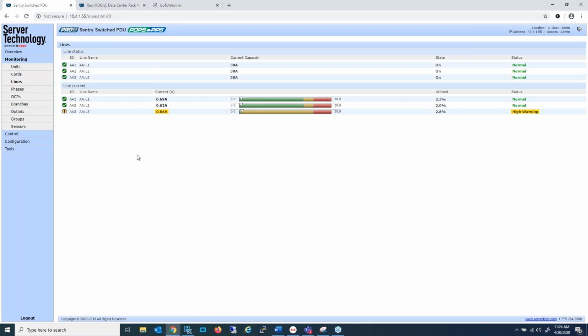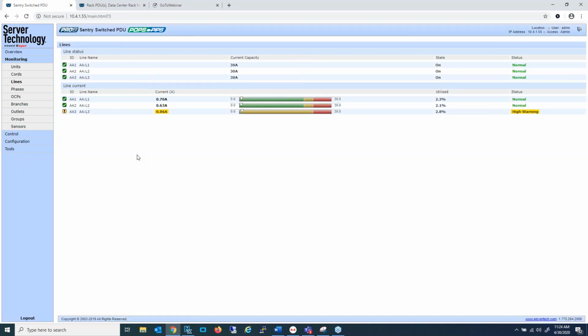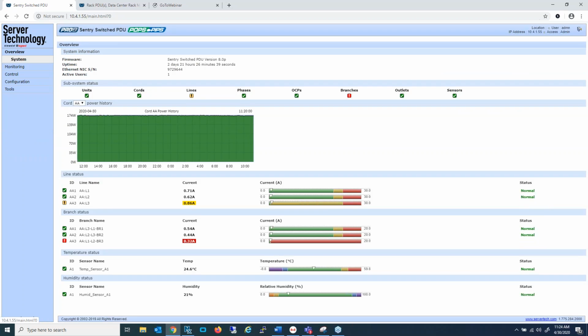Right. Okay. One of the options for you may be something about the PDUs. Something like PowerIQ software can give you management and alerting capabilities, not just at the PDU level, but a couple of elevations above. So you can set alerts for a rack or a row or a pod, or even at a data center level. If you already have PowerIQ, that's the place you would do it. If not, that's another option that you can consider.